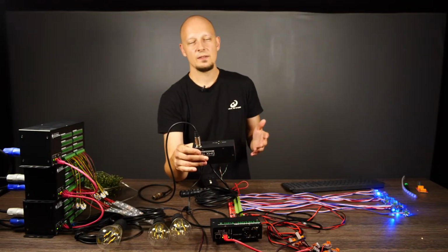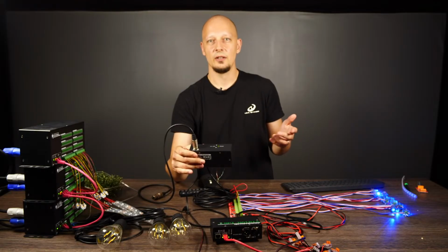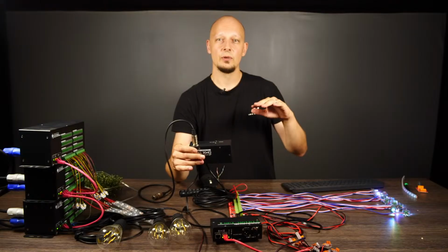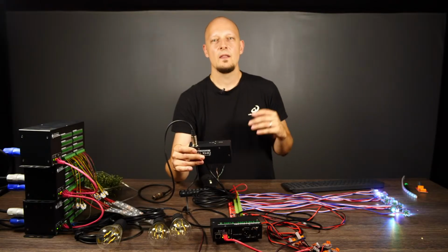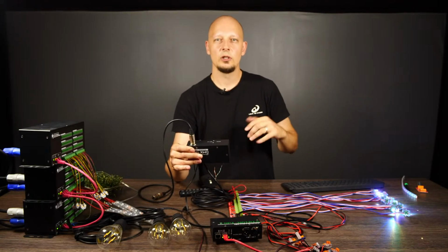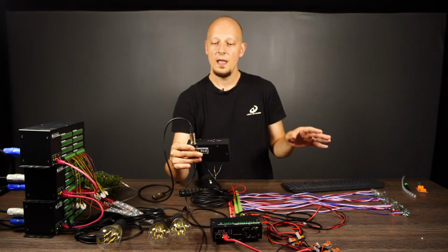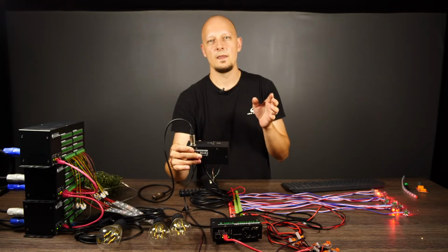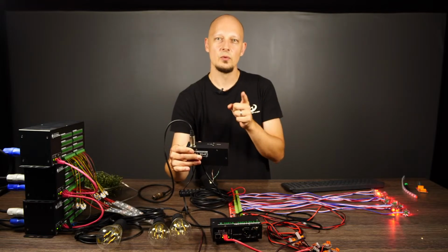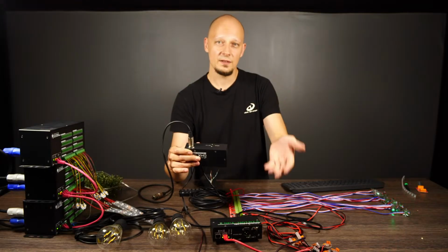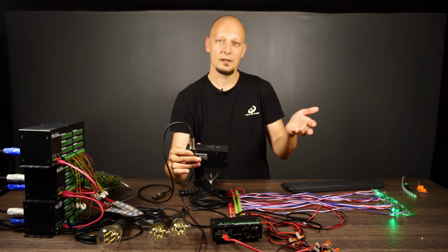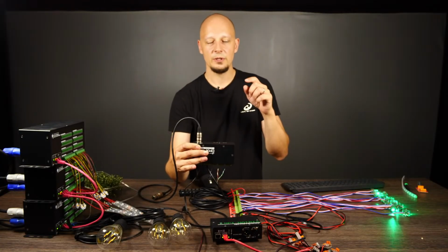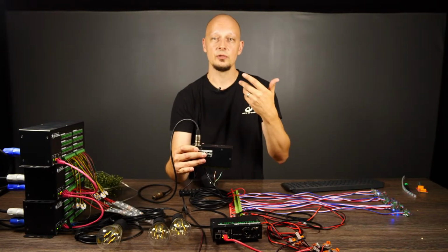And those buttons can really be any kind of switch where there is on and off position, and you can have up to 8 of those buttons. The first button or the first channel will always turn everything off, and then the remaining 7 buttons will trigger the animation from 1 to 7. So you have to have your effects stored on an SD card, prepared in advance or in LED Strip Studio software, and you will be then using DMX TRX to trigger those effects.